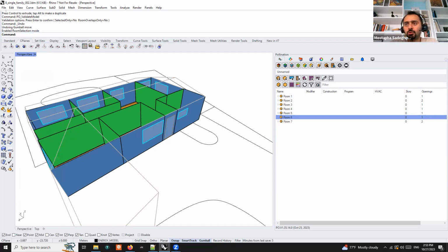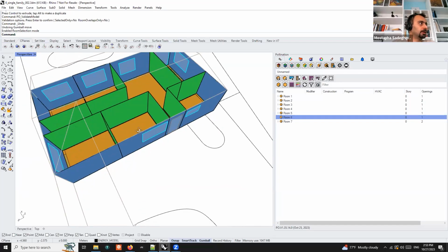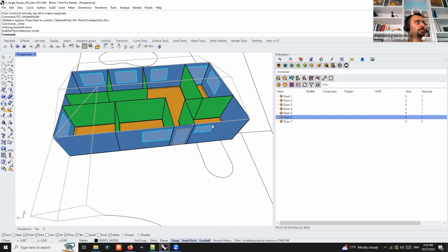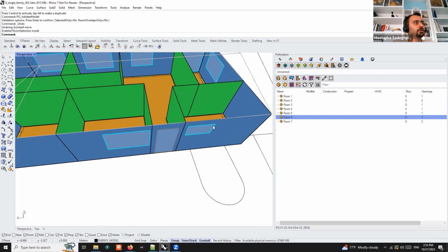Anyone else running into duplicate subface identifier error when validating after adding apertures? I don't think so. How did you model that? I love that you hit that error. It's hard to create that error, actually. I don't know how you created it, but the problem is you have two apertures that have the same exact identifier. That makes the model invalid.